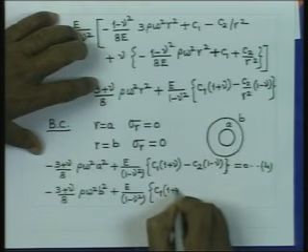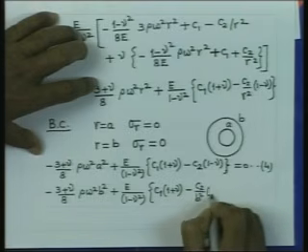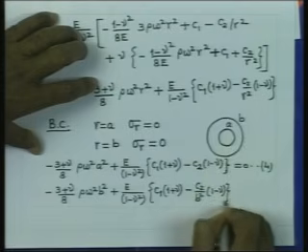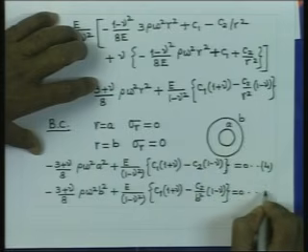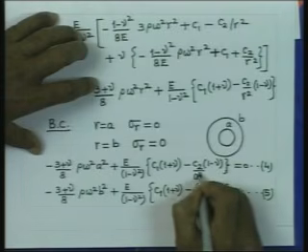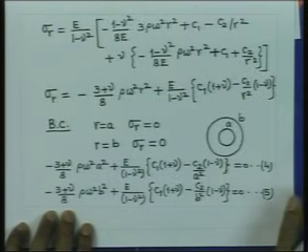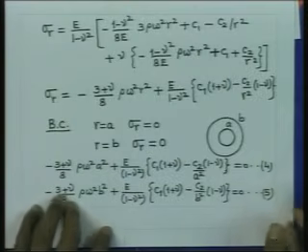(1 plus nu) minus C2 by B square (1 minus nu) equal to 0. So, let us consider that this is equation number 5, and herein please note that this is C2 by A square in the previous one. So, therefore, the two equations are very similar. In this we have A involved, in this it is B involved. So, these two equations are sufficient to solve for the arbitrary constants C1 and C2. So, from these we get the constants as follows.